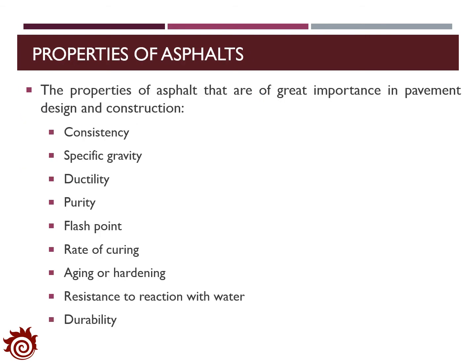The asphalt actually has a lot of properties which are very important for road pavement design. In this page, I list a set of properties we should take into consideration, including consistency, specific gravity, ductility, purity, flash point, rate of curing, aging or hardening, resistance to reaction with water, and durability. In the rest of this lecture, we will make a brief introduction about each of the properties.